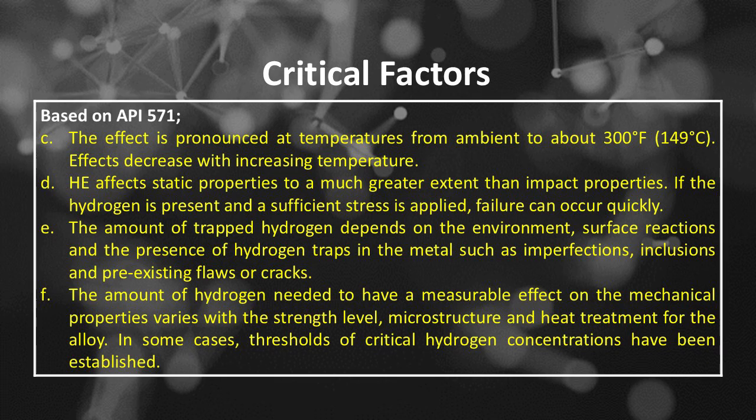Number D, HE affects static properties to a much greater extent than impact properties. If the hydrogen is present and a sufficient stress is applied, failure can occur quickly. Number E, the amount of trapped hydrogen depends on the environment, surface reactions, and the presence of hydrogen traps in the metal such as imperfections, inclusions and pre-existing flaws or cracks.